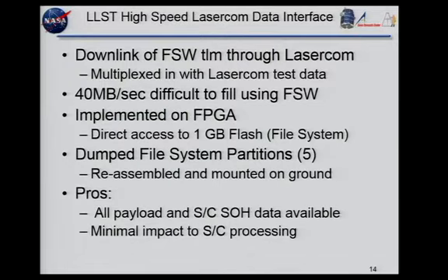And this just talks about the high-speed data link. What we did for the high-speed data link was a whole thing in itself. How do you get telemetry for it? How do you fill that telemetry frame with meaningful data without interfering with all the other things you're trying to do, especially holding your attitude so that you can do this laser comm experiment? We have to have really, really tight deadbands on your attitude control.